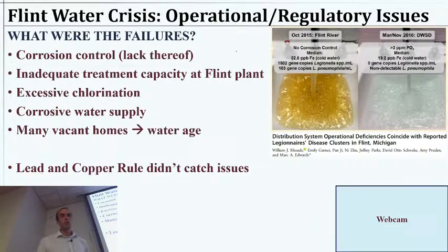That just means we are adding PO4 3-. That's a buffer. Maybe we add it as H2PO4 2- or whatever, but we just add it and we are adding protection. We don't want to add a ton of it. It's not good for the environment to have a ton of it discharged, but a little bit of it goes a long way and really protects.